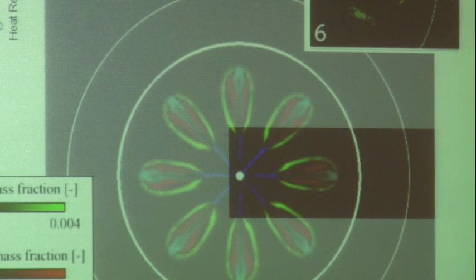The second stage combustion is characterized by plenty of OH, and that's shown in the green that surrounds the plume here. So we're looking at just one of the plumes here, and here's the experimental plume at that same time. You can see very good agreement in terms of the shape of the jet and even the thickness of the OH plume around the plume.